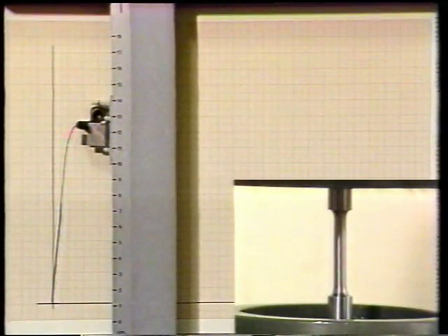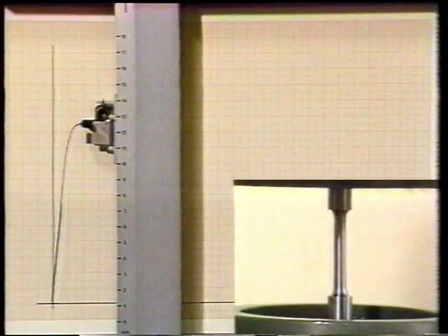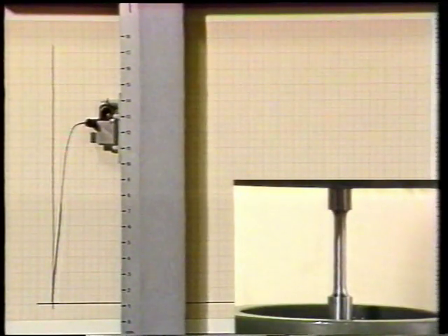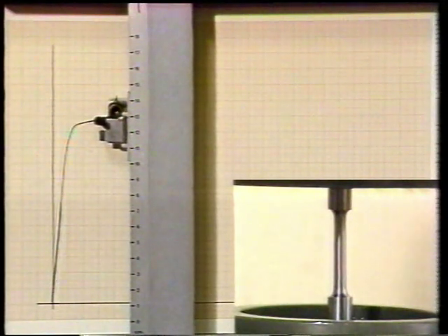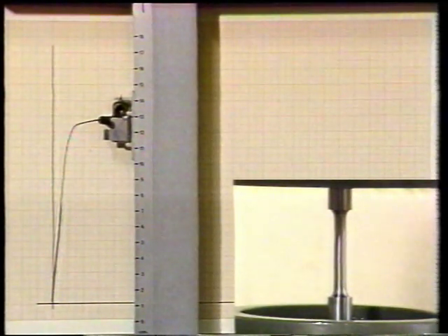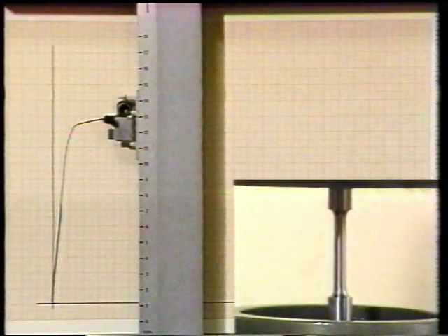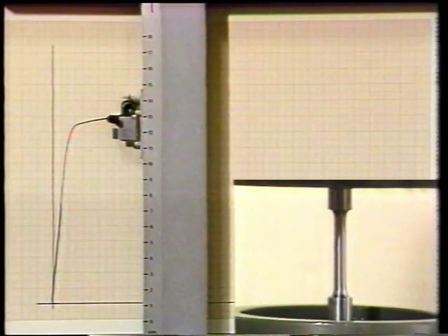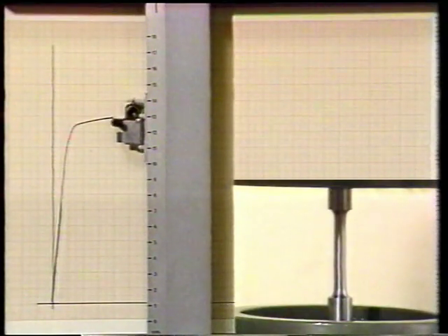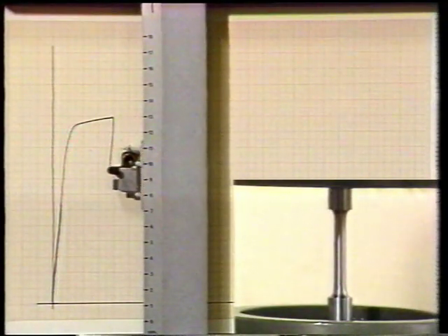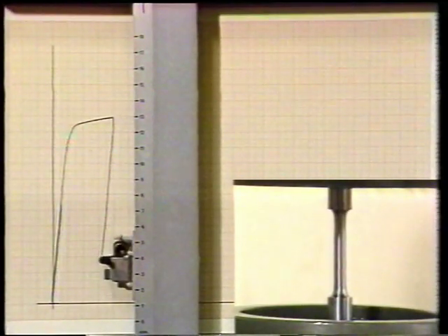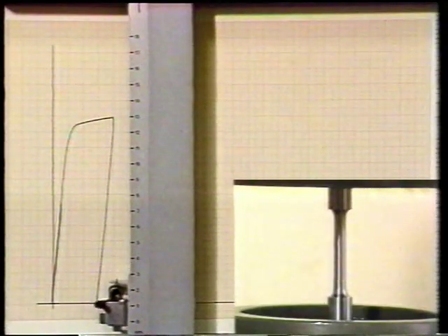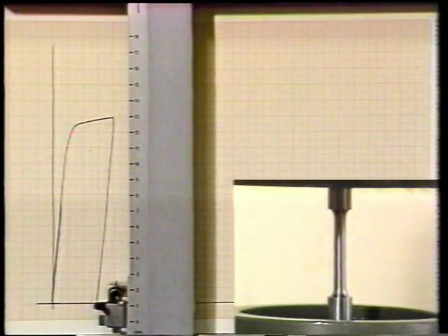There it is. We've come to the end of the elastic region, a slight jiggery motion as the steel yields. Now it begins to work harden in the usual way. The material is now deforming plastically. And if we take off the load, it should return down the same slope of the elastic curve, but when it gets back to the zero force axis, we've got a permanent displacement. So that shows the permanent deformation that's occurred in that part of the curve.